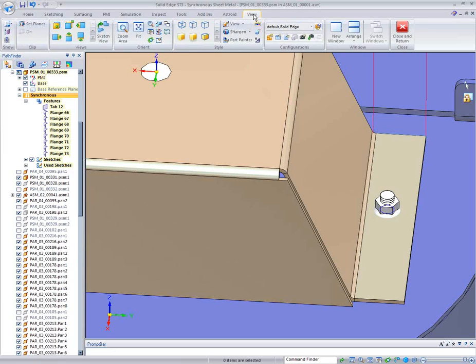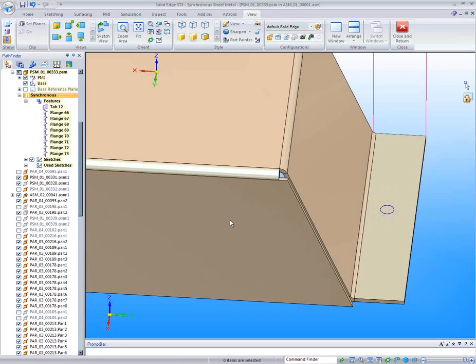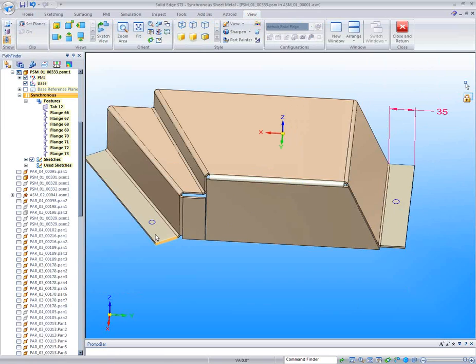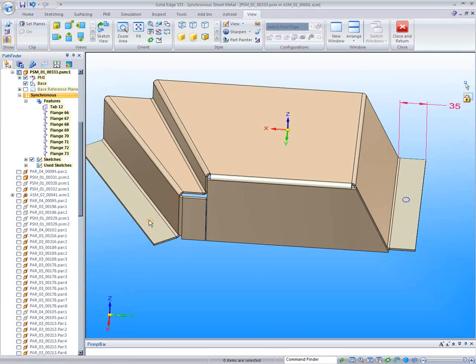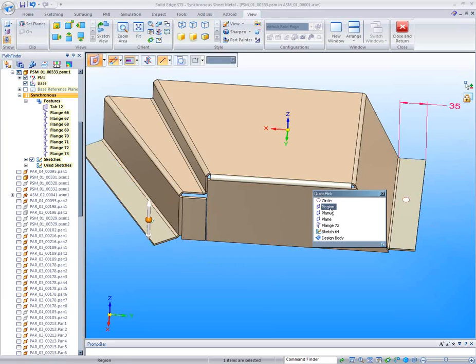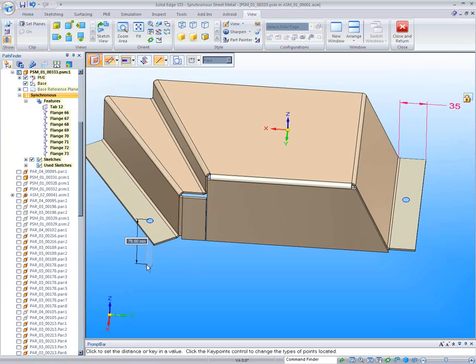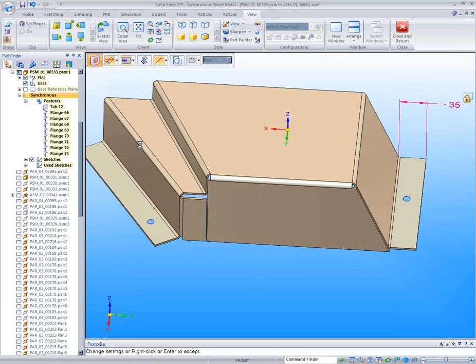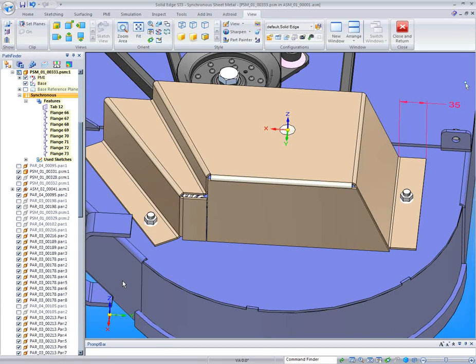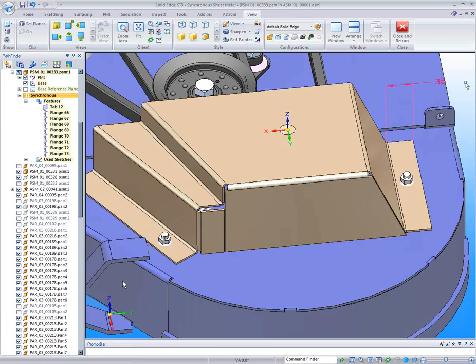Now, at this point, I'm going to hide the rest of that assembly so we can see more of what we were working on. I'm going to take this region, hit my space bar, come around, hit that region. So now I'm taking both regions at the same time, and I'm just going to bust a hole right through there, giving me exactly what I want. And now they're going to fit. Those bolts are automatically going to fit on that plate. I don't have to worry about whether that plate fits into this environment or not. So very, very strong, very, very powerful.